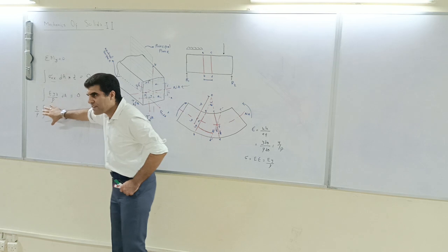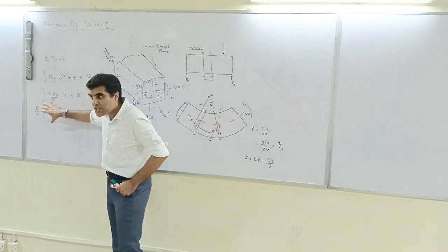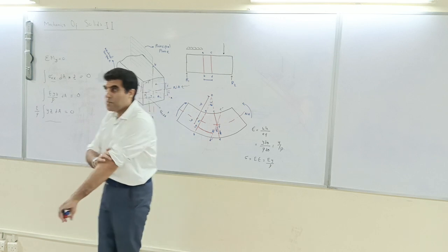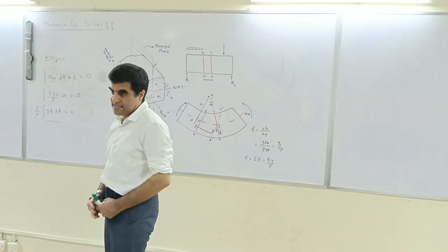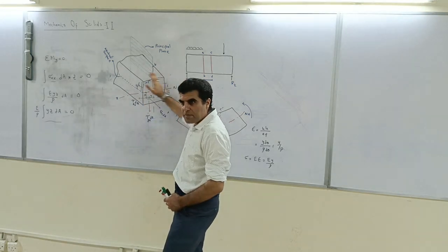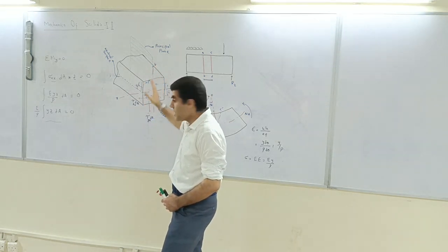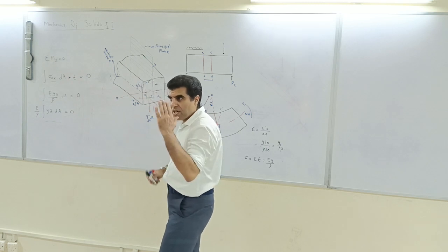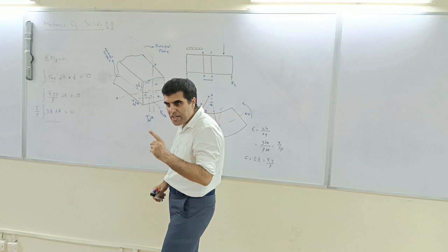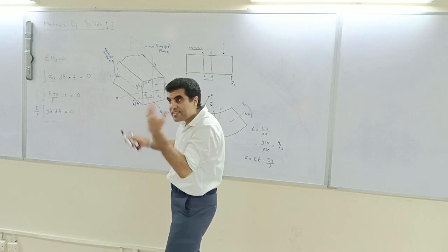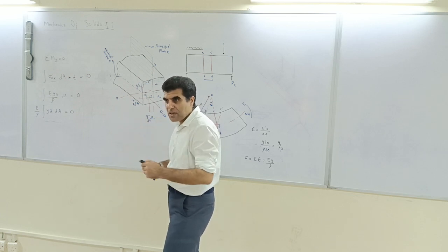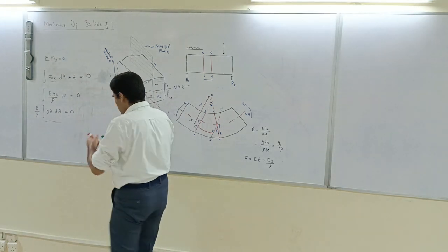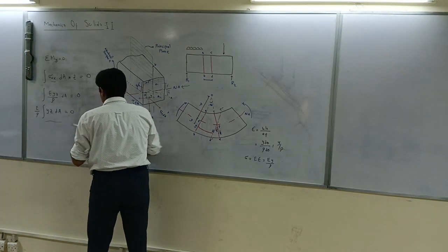Wherever you can do this sort of activity, those axes which give you product moment of inertia 0, those are called principal axes. In a rectangle, it's the same centroidal axes which are the principal axes. But it becomes tricky in the case of sections which have one symmetry, like a channel section, where it's again the same as the neutral axis.